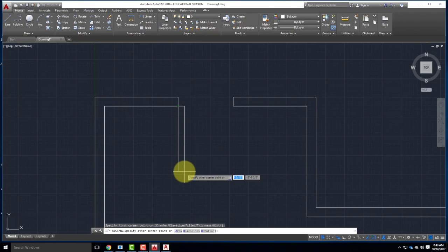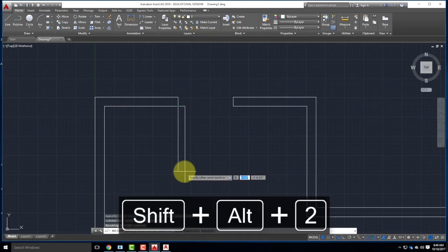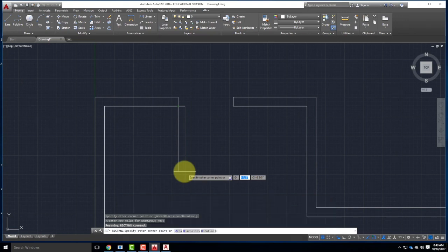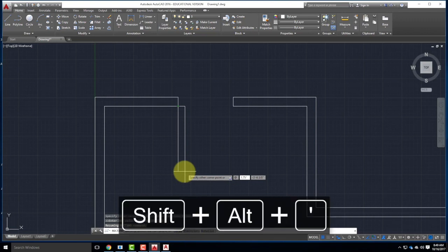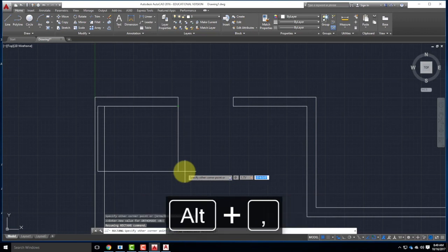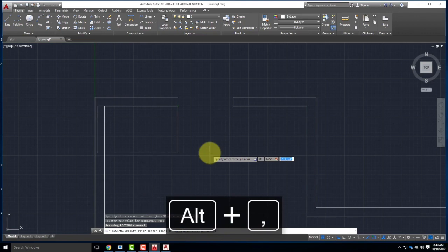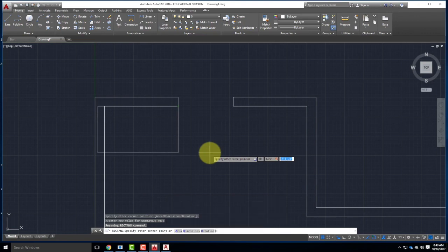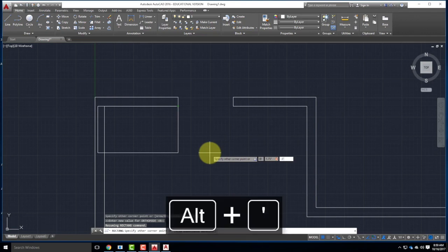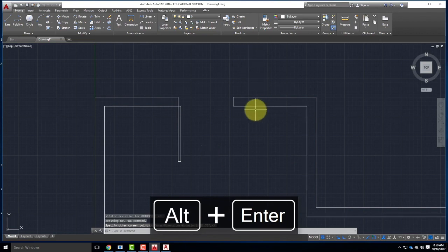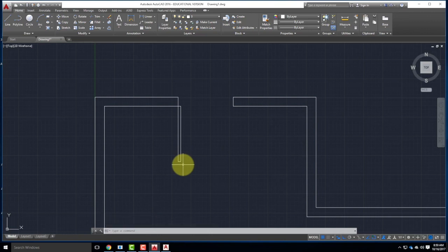So here's an opportunity to use those relative coordinates. So I'll type the @ sign. And this time, with the @ sign in place, I'm going to say 1.75 inches, comma. Oops, sorry. -3 feet, enter. There we go. So I was able to create that using those relative coordinates. So there's a perfect example of where using a relative coordinate is an easy solution to draw this.